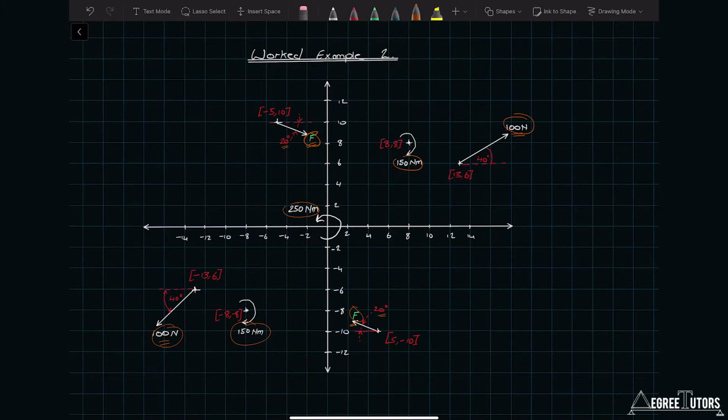And so by design within this question, the sum of the forces is actually already 0 because it's just made up of moments and couples. So there's no resultant force effect. What we have to do is work out really what's the value of F that makes the sum of the moments also equal to 0.